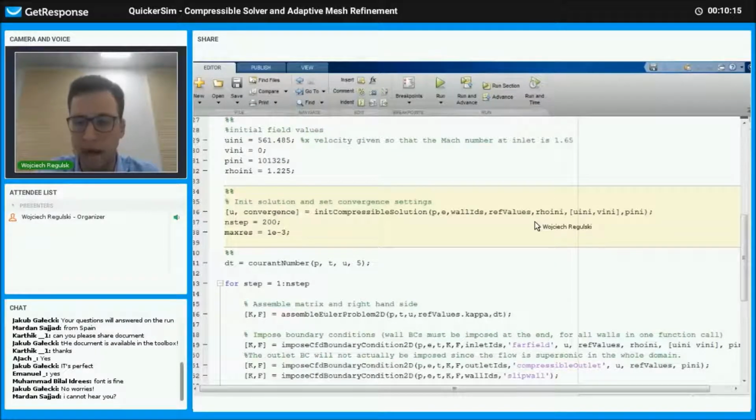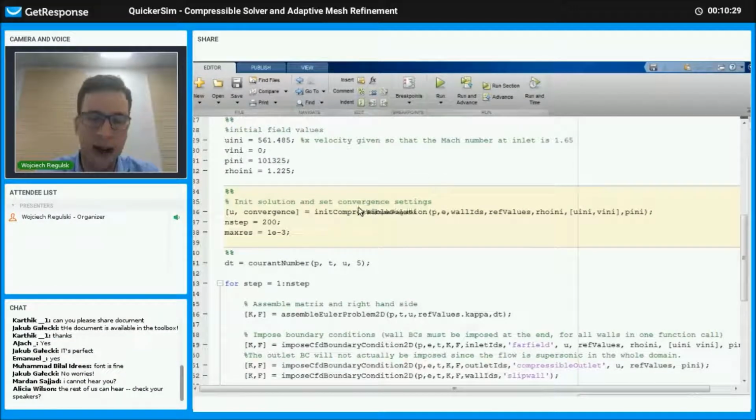Here it's a little bit different because not only do we need to generate those vectors, which is straightforward, but right off the bat we need to make sure that the values for the velocity that we generate do not have a normal component to the boundary. So that we enforce a non-penetration condition right off the bat.